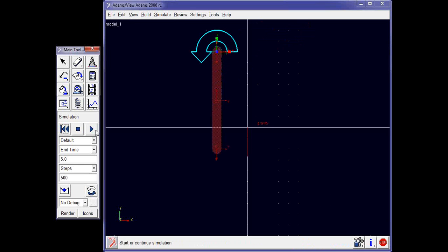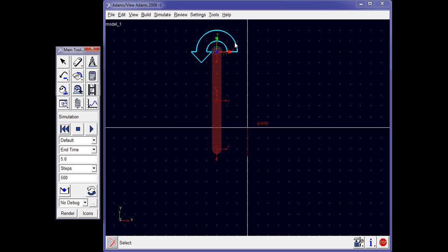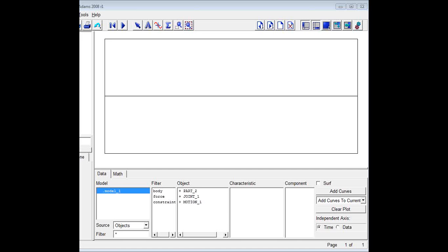So that's how I can model one thing. I had this one motor, it has some control design, and it has one link. What should be my motor's requirement? Go to this screen. I have one joint which has one motor over here. I'll say element torque, magnitude, and add it.